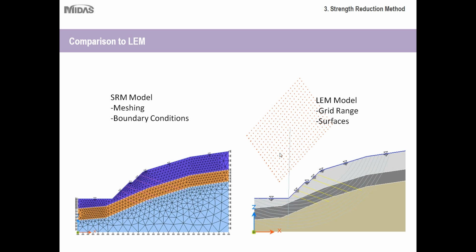And what the program will do is it'll take each of these points here and link it up to a tangent or a point on that failure surface, and create a series of slices for it and the factor of safety. So as you can see, it would be very repetitive done by hand, but what the program does is it does all of it very quickly. Within a matter of seconds, actually, the calculations are done.